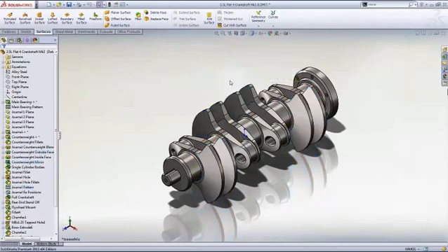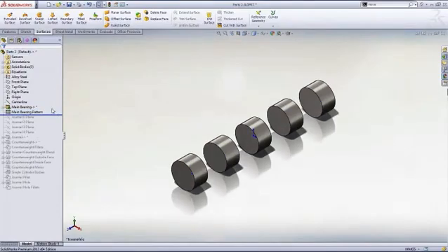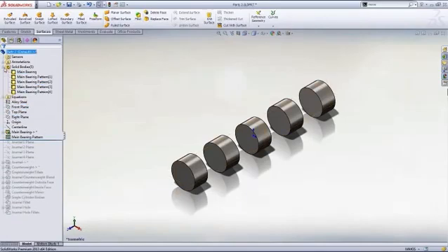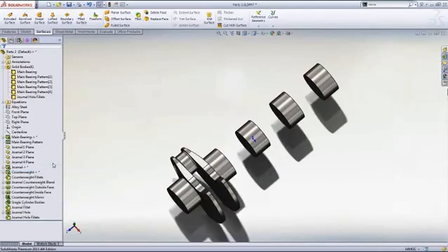I'm going to open this design in an earlier state to explore this concept. In this design, I've started with a simple cylinder for the bearing surface. Then I've patterned that, and you'll notice in doing so, I've created a part with multiple bodies. In fact, when I did this, SolidWorks revealed a folder containing all the individual solids. Next, I created the journal where the connecting rod attaches out in space, also as a separate body. This method makes it really easy to get the basic geometry created and then just fill in the rest with a connecting geometry, in this case the counterweights. I've also intentionally left the counterweights in the journal unmerged from the bearings, and we'll see why I did this in a moment.